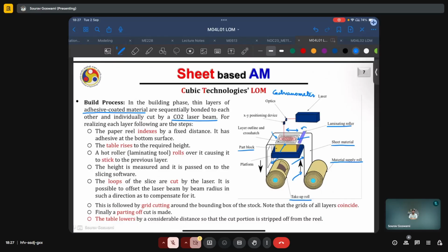For instance, the typical so-called red lasers, some 976 to 1000 nanometer in wavelength, interact well enough with iron-based, nickel-based, or titanium-based alloys, but fail to print or deposit aluminum and copper-based alloys satisfactorily. However, lasers of considerably shorter wavelength, such as blue lasers and green lasers, do the job really well.